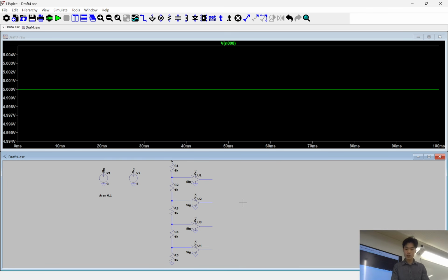With this, we can do this with something we call a priority encoder. It takes the most significant bit from each of these, in which case it's going to be the highest value, which is high. And based on that, if this one's on, I'll get 1, 1. If this one's on, I'll get 1, 0. This one, 0, 1. This one, 0, 0. That's what I want to do. So we can add some logic gates here.